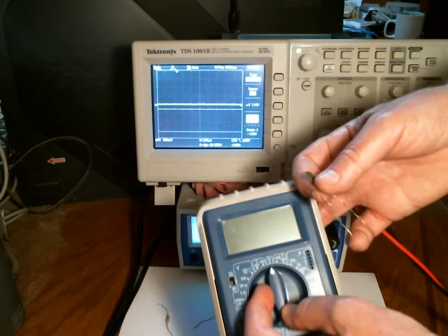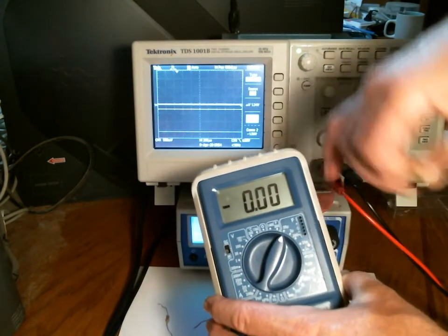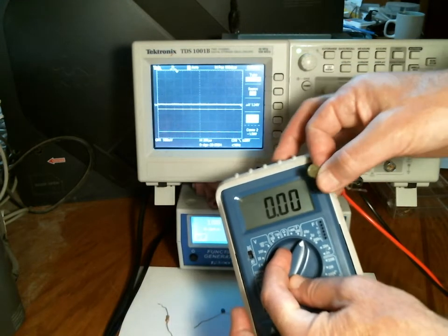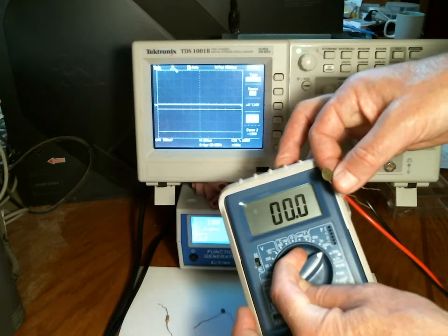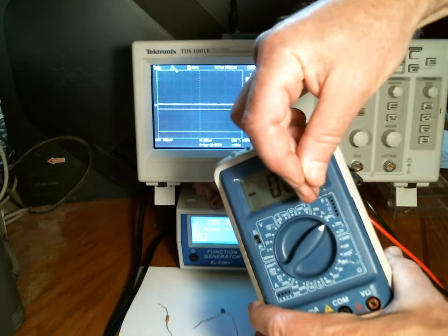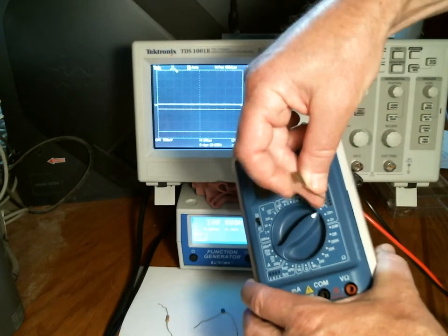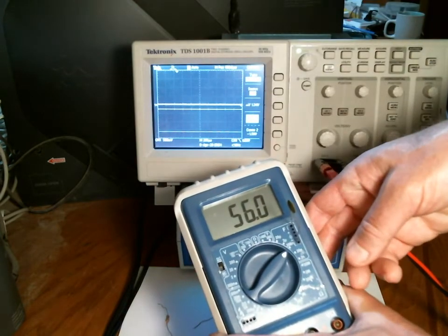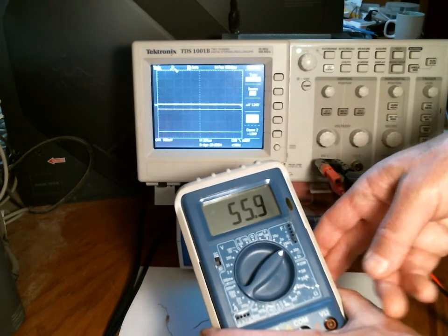On this multimeter, it has these scales marked F for farads. This thing claims to be 50 nanofarads, this green capacitor right here. So I'm going to put this on a 200 nanofarad scale. And then it has these holes here. So I'm going to stick the tails of the capacitor nice and deep in those holes to get a reading. And it tells me that it's 56 nanofarads, which is within about 10% of what we expected.